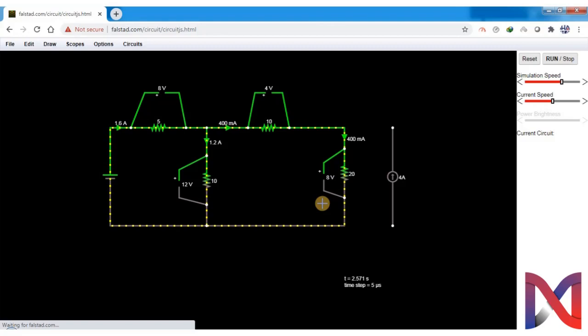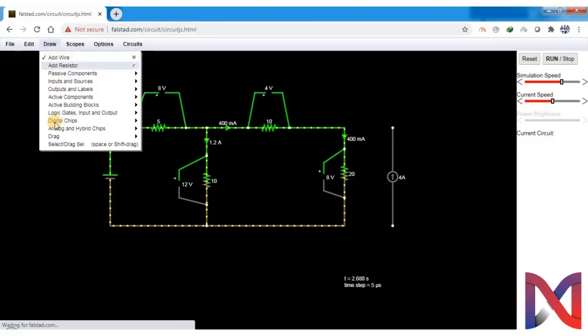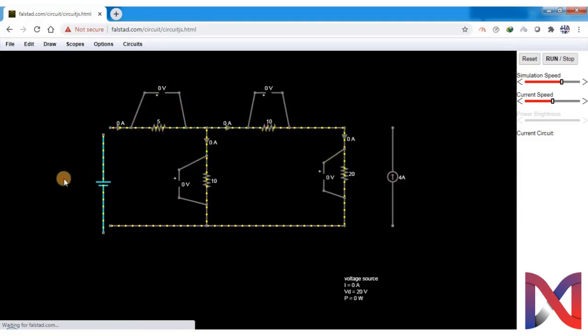Now, the second step was to open circuit the voltage source and connect the current source with the circuit. So we will do as directed. We will disconnect this voltage source. So I'm going to drag it further from here and I will short circuit this point where we connected our voltage source.